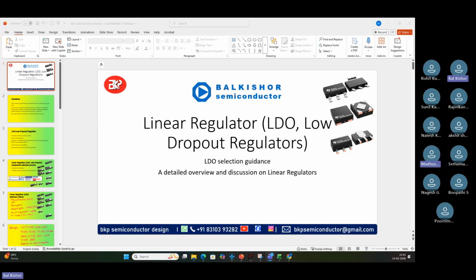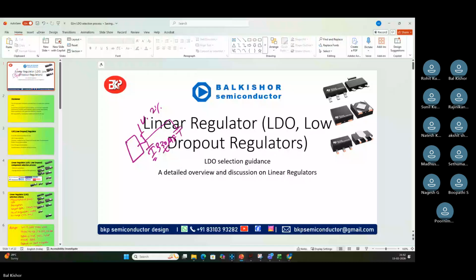Like in FPGA applications, sometimes we need to have a very high value of capacitor because of low voltage output. Okay, like there we have 1 volt output. So for 1 volt output, if you put an electrolytic capacitor of 330 microfarad, you won't get a very good result. And FPGA requires around a 2% output tolerance. So for that, this might not serve you a good purpose. So the beauty is in going ahead with a polymer capacitor or tantalum capacitor. Okay.